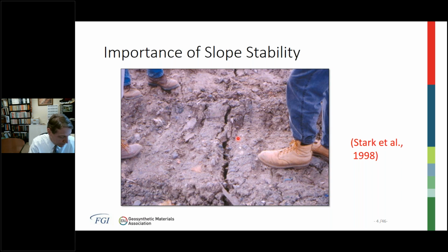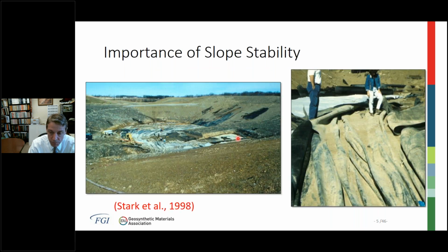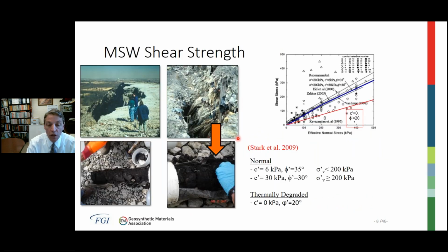Okay, great. Let me see if I can follow this one a little bit from David Lutz. It's a good question. I just want to make sure I ask it correctly. Does the residual shear strength get plotted on the acceptability curve with the peak interface strength to determine an overall acceptability graph, or are these standalone and independent based on the location where the material is used? Does that make sense, Tim?